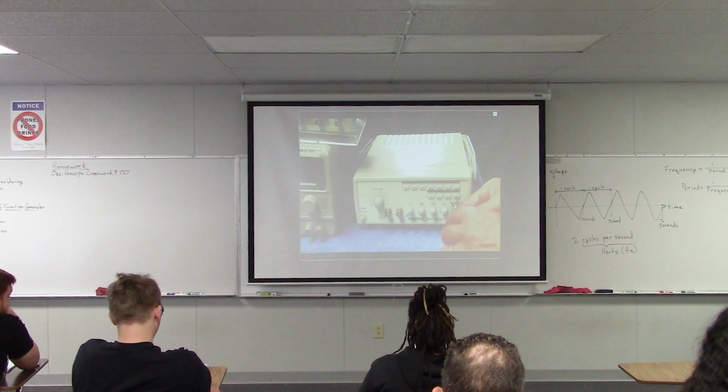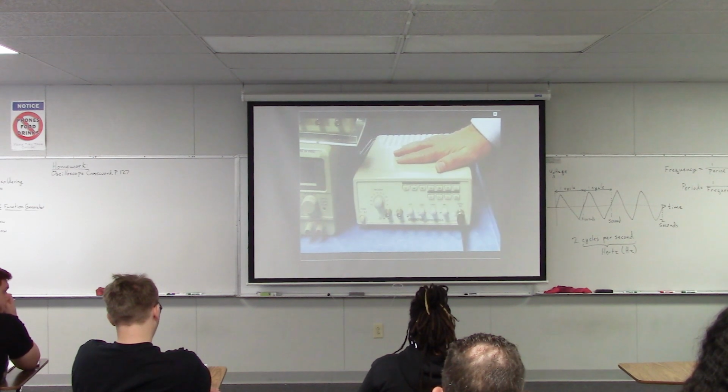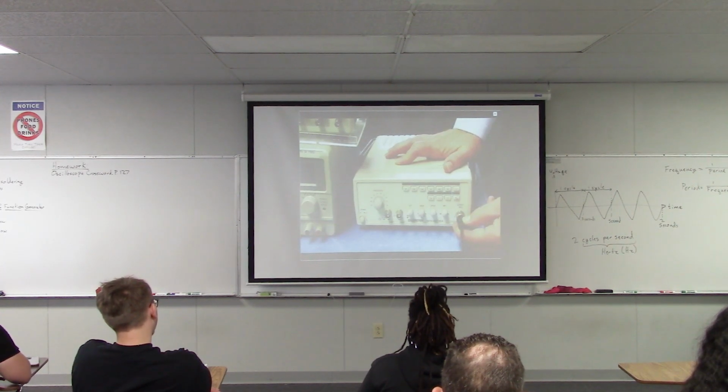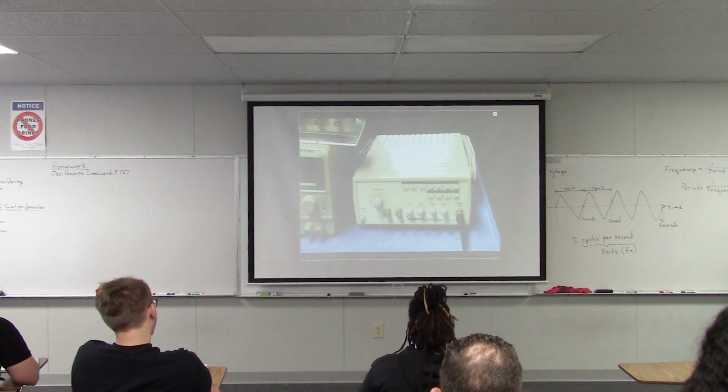So you line the bump up with the channel, you push it in, and then you twist the connector. Again, you line up the little bump with the channel, push that in, and then you take this little collar on the BNC cable and you twist it and make a good connection that way. And then that is connected.